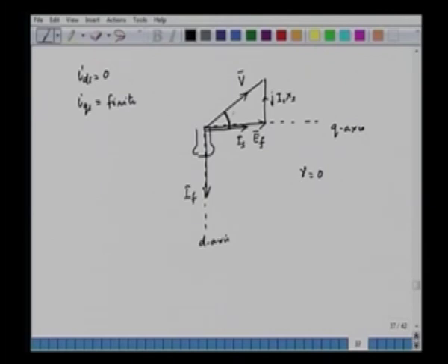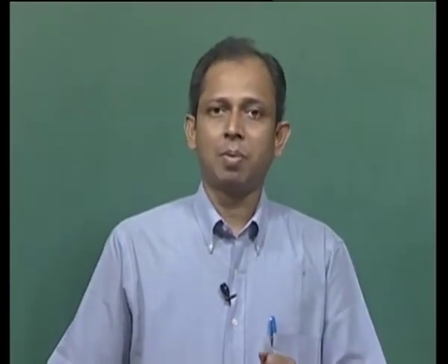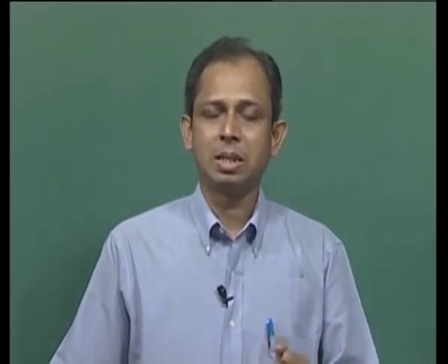So, this is the power factor angle, that is theta. The current lags behind the applied voltage, and hence in a vector controlled synchronous motor drive the power factor is lagging. However, the torque response is quite fast. If we want to have a torque change, we can change IQS and the torque changes instantaneously.